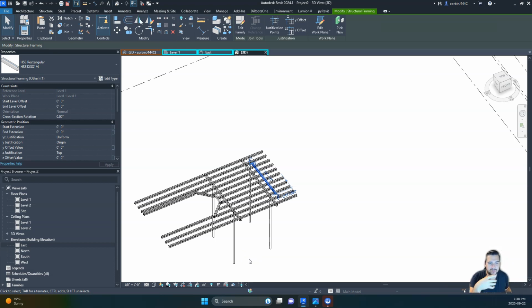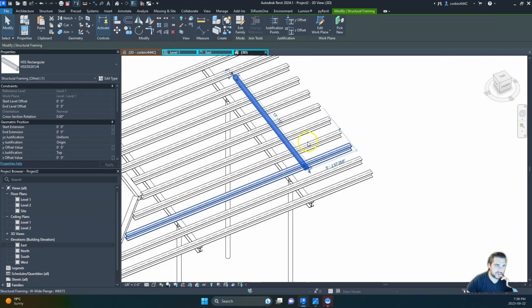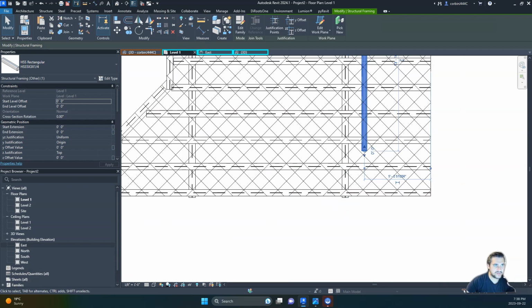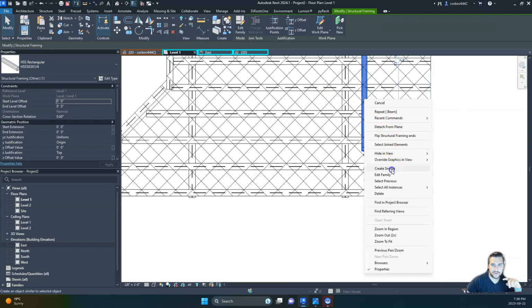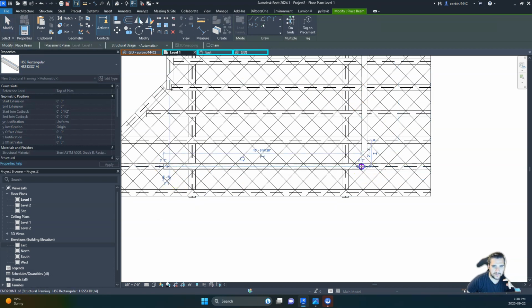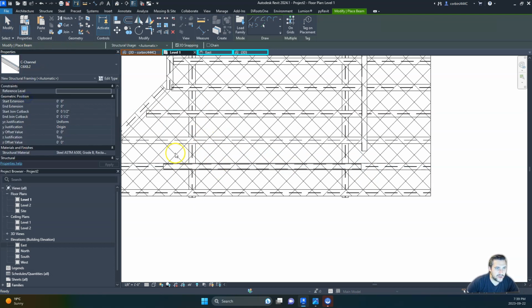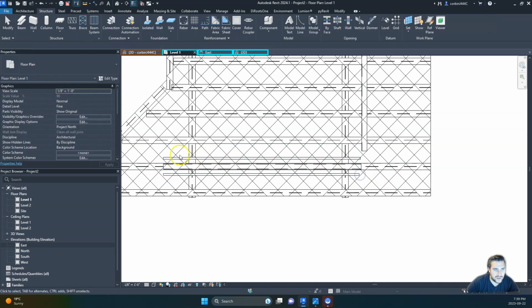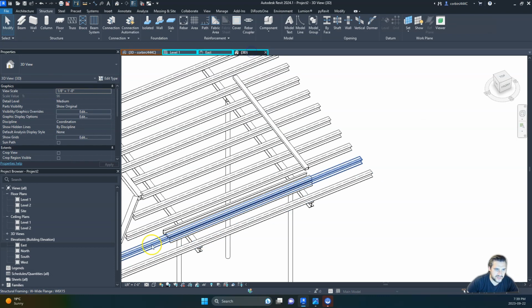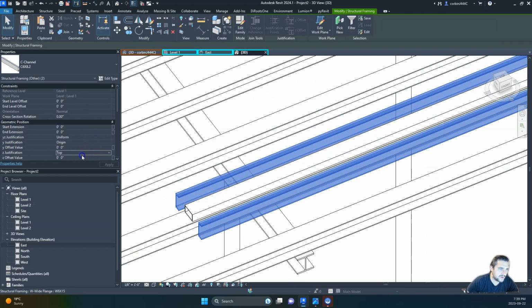And when we get the engineering, you just follow and place the beams exactly where the engineer wants it. So let me know if you have any questions with that, but that's how we typically model dock structures. Maybe one caveat, actually, I'm going to mention one more thing before I finish, is, sometimes we have this tubular steel going parallel like this, or something like this. And what we might do, which is why we brought in that C channel, is we would put that C channel on either side, and that's just to pick up the dock boards like so. So we put that C channel on either side like that. And we just got to make that -3 inches, and that's how we get the dock boards to sit next to the wall like that, like so.